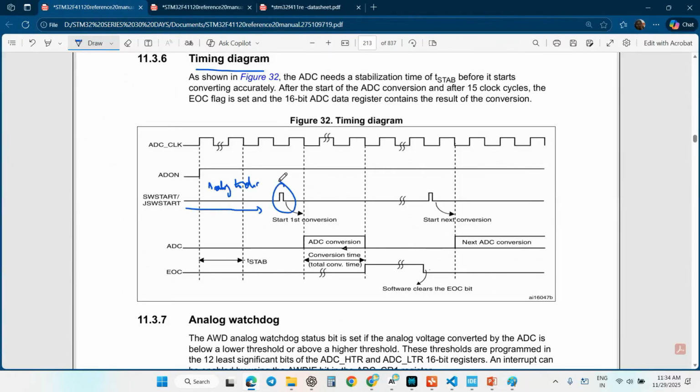Here the digital conversion result, for example, I'm getting 450, within the resolution range of 0 to 4095, since it is a 12-bit ADC. I got one conversion. The next conversion value is 1000. I'm just increasing it to 1000. So the conversion has started, and we keep getting conversion after conversion.